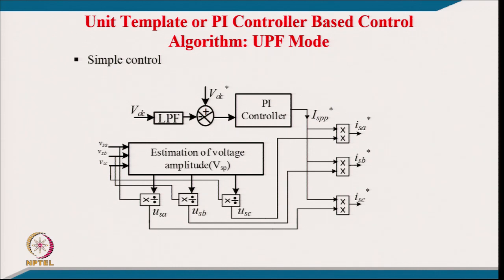Now, sensing the supply voltage here, I mean these three supply voltages, we might be sensing not the phase voltage but the line voltage, and from the line voltage we have to estimate the phase voltage. That relation also we would like to give there. Moreover, these voltages may also be distorted or unbalanced, which we will talk about a little later. At the moment we will not talk about it.